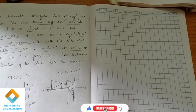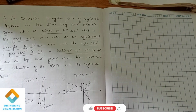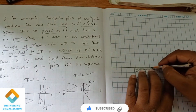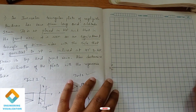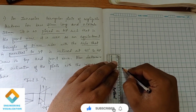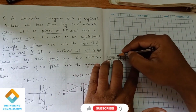So I'm proceeding with the question, so all of you carefully follow it. This condition is correct. First I will draw an XY line. Drawing the XY line is compulsory. VP, HP. First I'm constructing the isosceles triangle. First I consider the base edge, that is 25. After constructing the base edge 25 exactly, I will show the dimensions initially.